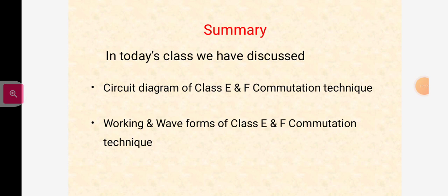Static circuit breakers, and also the SCRs are used in transformer tap changers and static contactors in industrial power system. Solid state controllers for mine winders, cranes, elevators, lifts, excavators, etc. And also the GTO SCR is used in electric traction, meaning railways, because of lesser weight, used in adjustable frequency inverter drivers, and also in rolling mills, robotics and machine tools to obtain high performance.